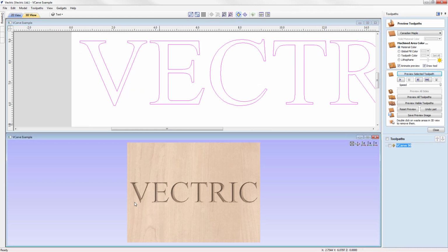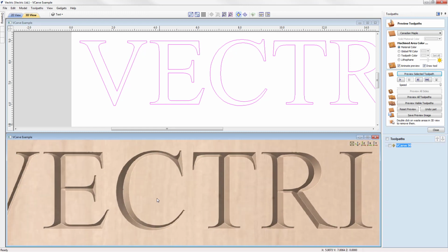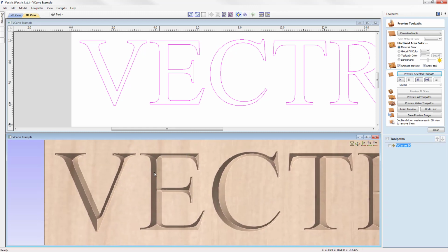Okay, so here is the E vector, and if we zoom in on the preview of that toolpath here, we can see that the two vectors here are further apart, and here you'll see we are getting a much deeper cut there. We're cutting that just around 0.195, and then here you can see that the vectors are closer together, and so here we're getting a shallower cut where we're getting kind of 0.7, I think, is the maximum depth there.